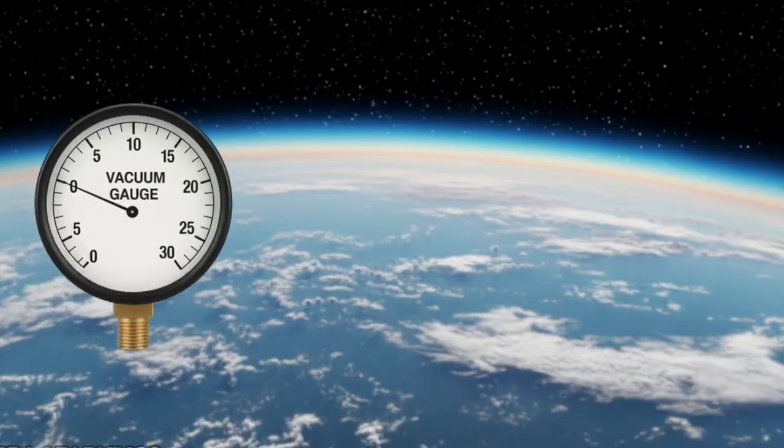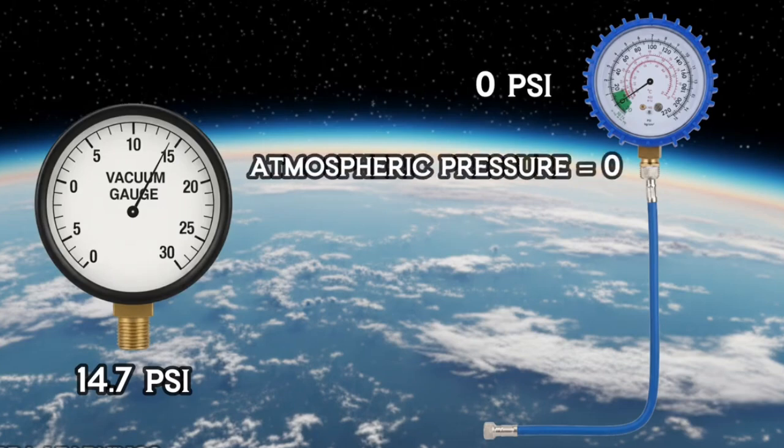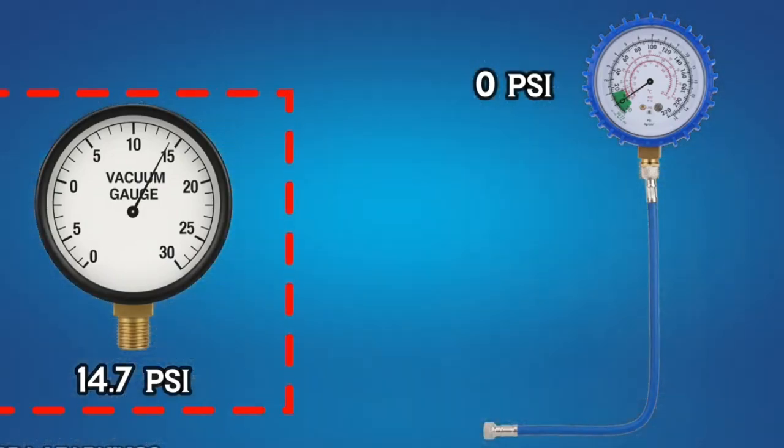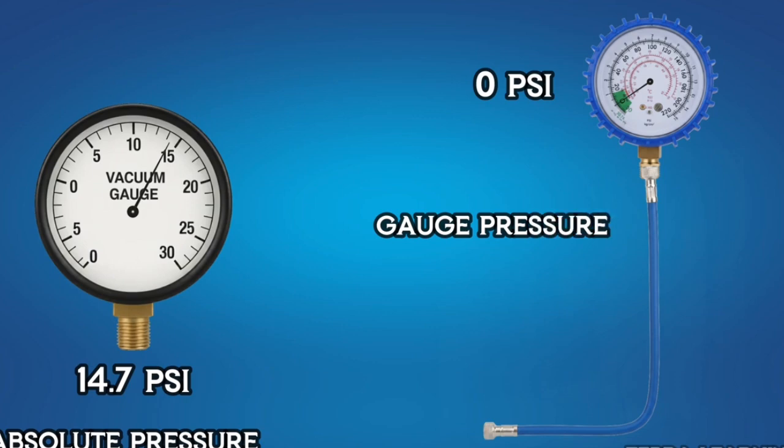The atmospheric pressure around us is 14.7 psi. But when we connect a manifold gauge in open air, it doesn't show 14.7 psi, it shows 0 psi. That's because the gauge considers atmospheric pressure as 0. So, when a measurement includes the atmospheric pressure, we call it absolute pressure. And when it ignores atmospheric pressure, we call it gauge pressure.